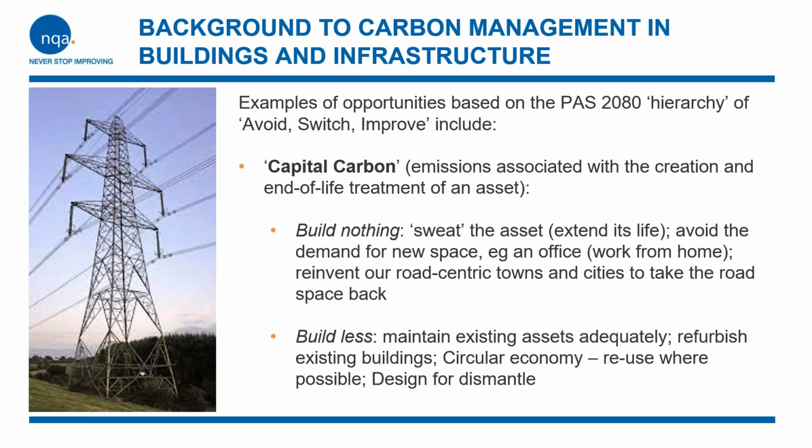So capital carbon, straightforward enough, that's the emissions associated with the creation and the end of life treatment of the asset, the building or the infrastructure. And we have options. We can build nothing, so for example, sweat the asset, in other words, extend its life, for example, a road or a building. Avoid any demand for new space, so offices, for example. Think about the designing and the planning side of towns and cities. We can build less as well. We can maintain our existing assets adequately, refurbish existing buildings, apply circular economy principles. I'll talk more about that very shortly.